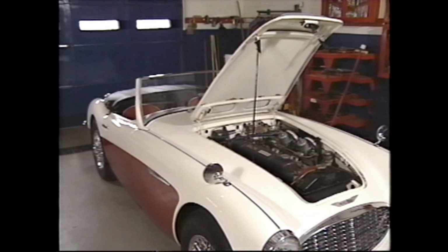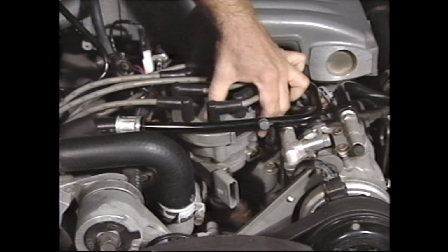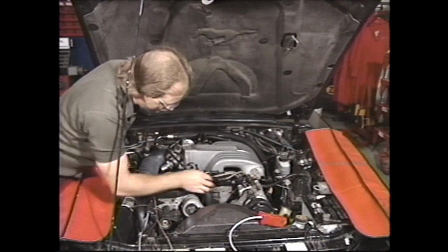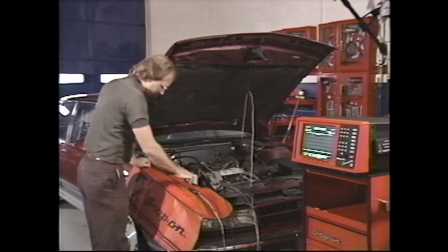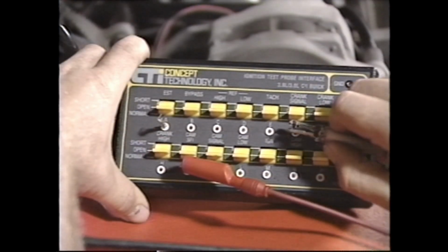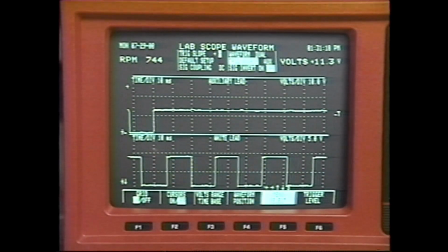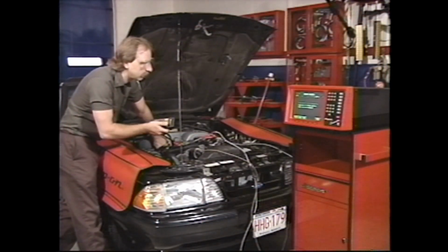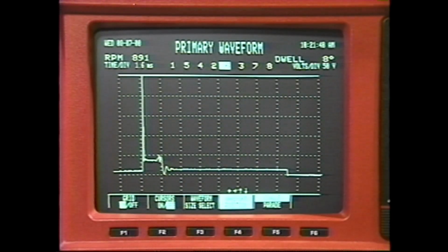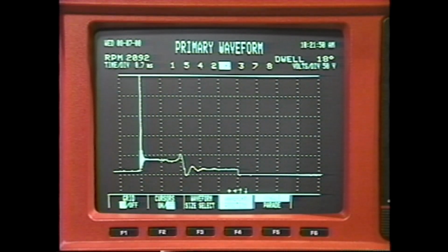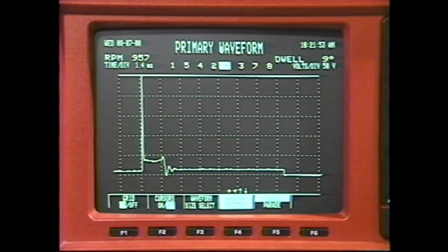Older ignition systems use breaker points to open and close the primary circuit. Electronic ignition systems use electronic means to control the flow of primary circuit current and ignition timing. Modern ignition systems are featuring more and more computerized control units as automakers strive to integrate engine systems. The main thing is that in both of these ignition systems, the principles of producing high voltage through electromagnetic induction are exactly the same. The basic waveforms for the primary and secondary circuits are similar.